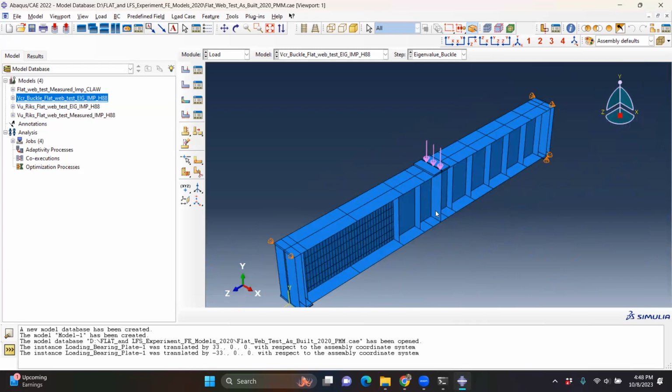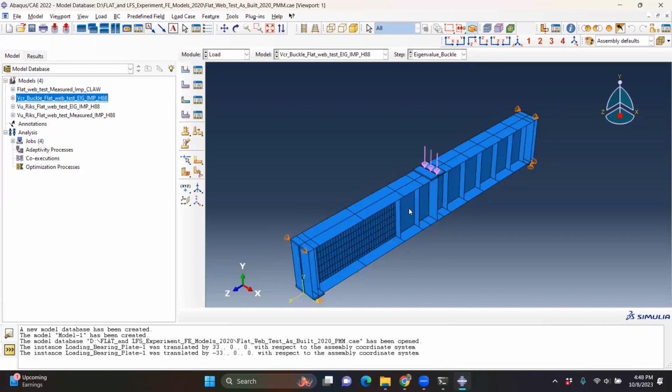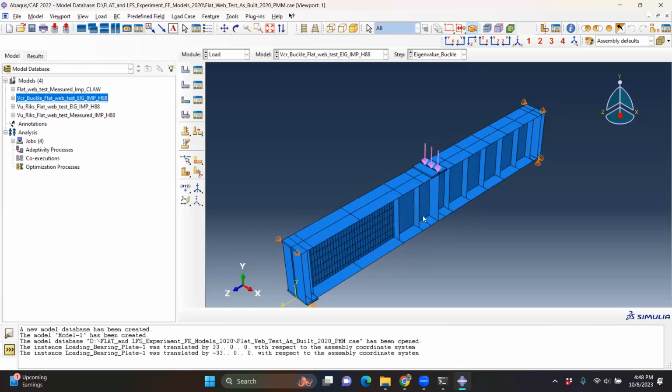So you will take what that area is, which is 1 inch multiplied by 33, which is that width, that's the area. And so 1 divided by 33, and that will be the ABAQUS applied load that you will apply on your model for your 3-point bending model. So that is how you quickly go about doing the bearing plate modeling.